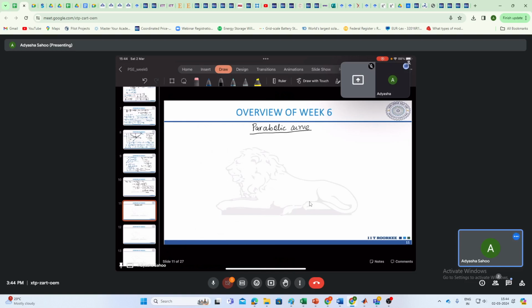So for a parabolic curve, basically we take that your d is much less than your L. So basically for your short span line, your sag is very small, and we had seen T max minus T min was w times d, but since d is also small, we take this as small or nearly equal.